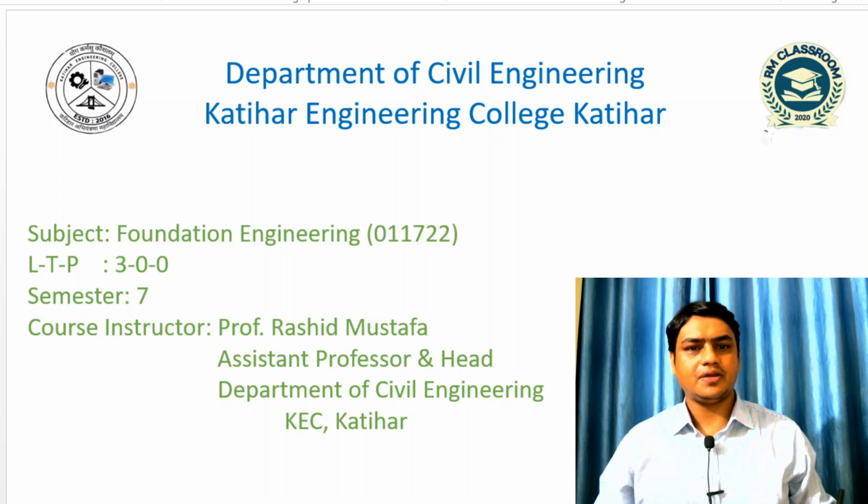So dear student, today I have discussed the analytical method, and in the analytical method I have discussed the three modes of failure due to the shear failure pattern. These three modes of failure were, the first one, general shear failure, the second, local shear failure, and punching shear failure. About general shear failure, I told you that this type of failure occurs in dense sand and OC material, meaning over consolidated material, and the relative density is greater than 70% and the angle of internal friction is greater than 36 degree.